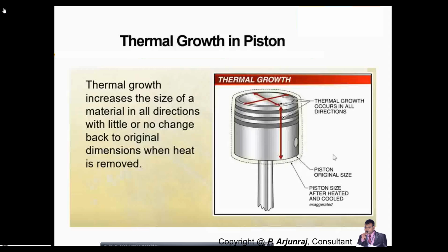Basically, the thermal growth is going to affect the piston because you get the expansion of the piston when it is subjected to high temperature. So it's very important to maintain the temperature. If you use the coolant system, you cannot completely avoid the piston size growth after heating, but at least you can maintain it. Hence it is very important to look for cooling and lubrication.